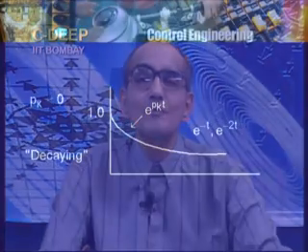Whether it's as simple a thing as a resistor and Ohm's law, V equal to Ri is okay provided the current is not too large. A very large current in the resistor will simply result in heating, and the heating will go on accelerating or cascading, and the resistor will finally burn out. It will no longer remain as a resistor obeying the law V equal to Ri. So a pole of the transfer function which is positive is bad from this point of view.